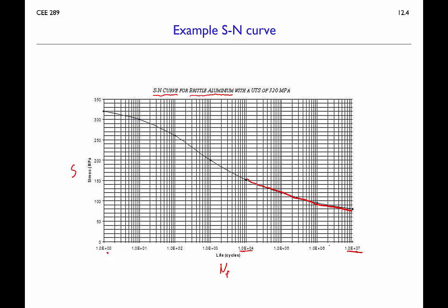And then our question is a couple things. We've got to think about how we might actually calibrate something like this, and we need to think about what this means for stochastic loading. Of more interest for our class here today is that we need to think about, well, what if the loading is variable in amplitude, right? So the real world is not giving our materials constant amplitude loading. There's going to be some large amplitude cycles of loading and some small amplitude cycles of loading. So how do we take this type of concept and extend it to this variable amplitude loading case? So let's dig into that a little bit.